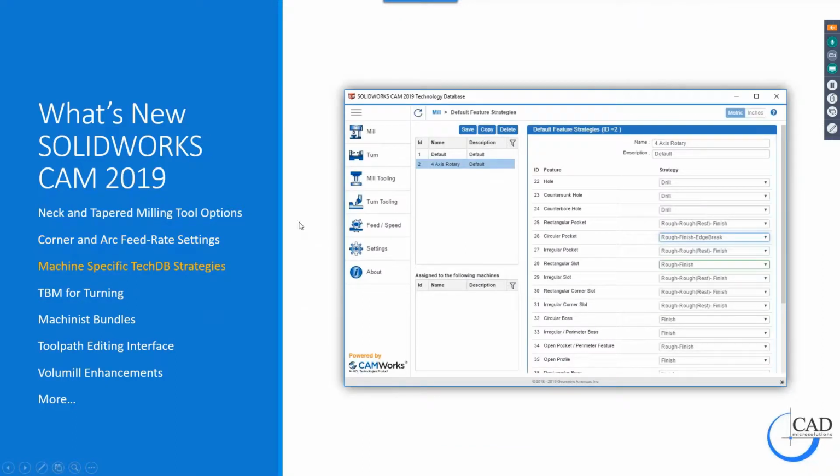Machine-specific technology database strategies. This is a really great addition to the new software. Basically, what we can do is set strategies for different machines. Let's say, for example, you're programming both a milling machine and a laser machine. Those two machines are going to have totally different strategies associated with them. With a laser machine, you're really just using a contour tool path to cut all of those. So with these strategies, we can set every strategy for that laser machine as a contour tool path, and that would be linked directly to the machine. Every time you select that machine, the default strategies show up with it. So that's a really great option.